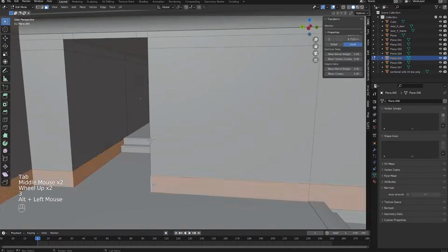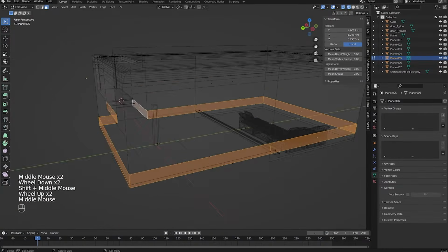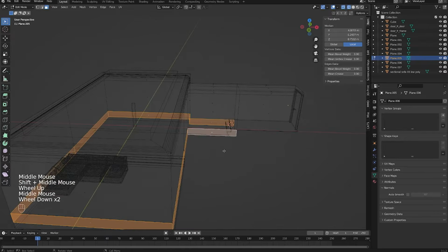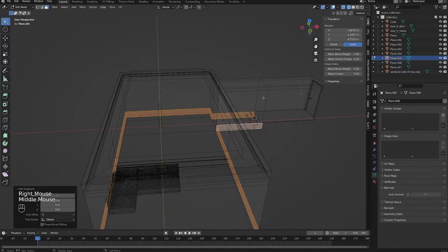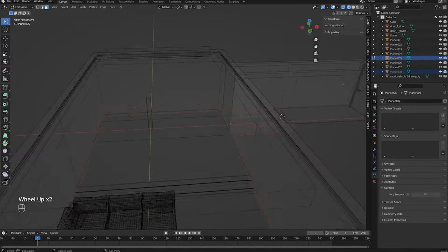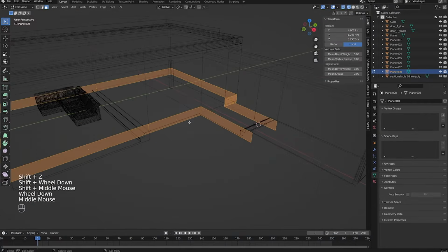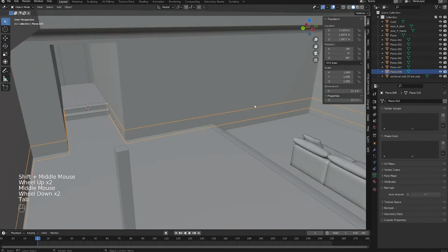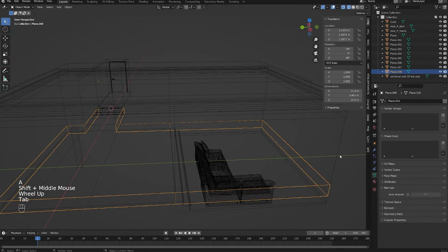So let's look at our wall. Let's see, can we do anything here with this? I think this is the simplest loop that we can grab, and we can just edit off of here. So let's grab this loop. Let's press Shift D to duplicate, right click on the mouse to bring it back to its original point. Press P to separate. P is the shortcut for separate. Press selection, and now if we go back to object mode by pressing tab, we can select this. Going back into edit mode, we can now make our changes to this. I would say let's get rid of all the edges we don't need, but we actually might need those. So let's keep those there.